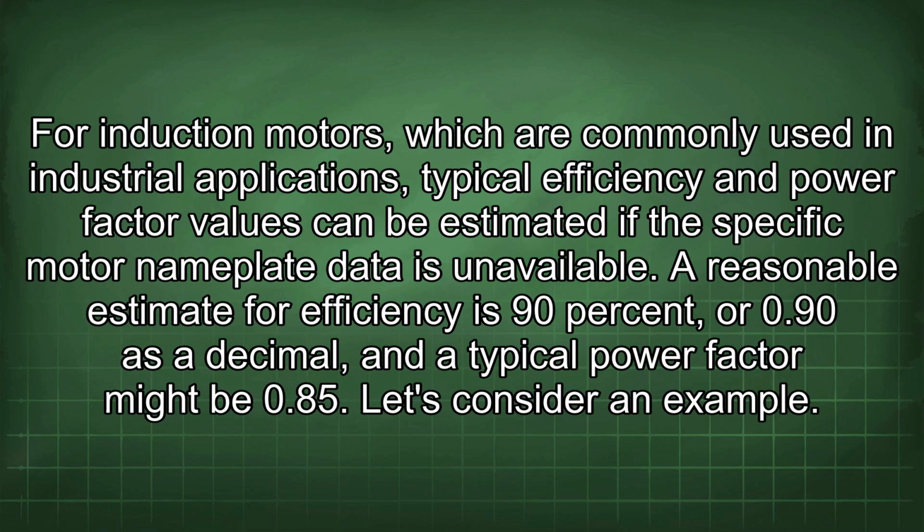For induction motors, which are commonly used in industrial applications, typical efficiency and power factor values can be estimated if the specific motor nameplate data is unavailable. A reasonable estimate for efficiency is 90%, or 0.90 as a decimal, and a typical power factor might be 0.85.